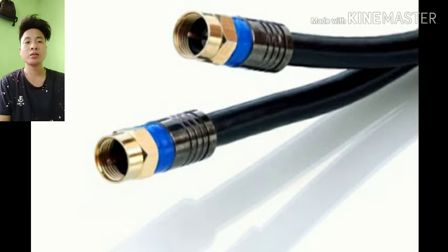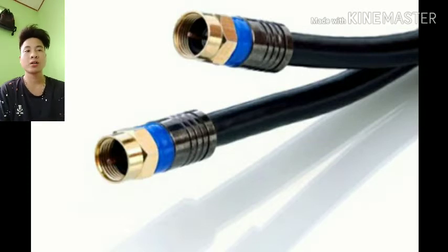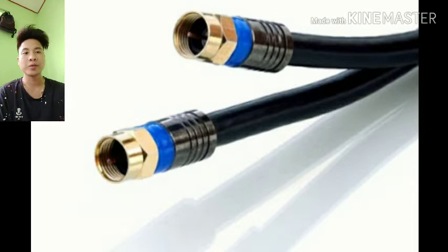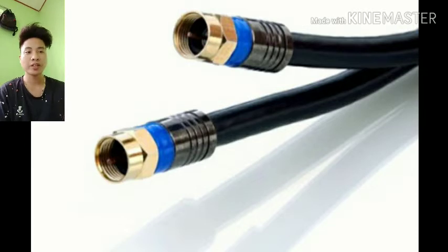Coaxial cable. So, wireless installation. Coaxial cable attaches antennas to wireless devices. The coaxial cable carries radio frequency energy between the antennas and the radio equipment. So, cable internet installation. Cable service providers provide internet connectivity to their customers by replacing portions of the coaxial cable and supporting amplification elements with fiber optic cable. However, the wiring inside the customer premises is still coax cable.